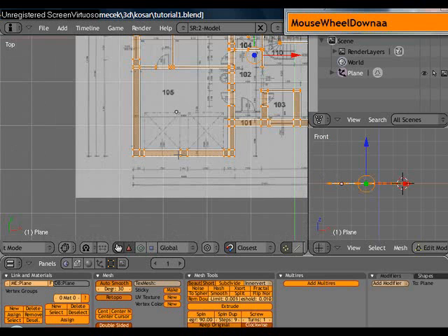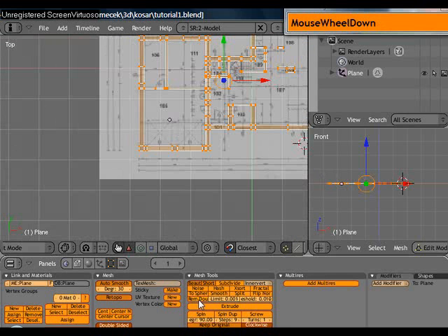To do that, I will select all the vertices, and I will use this Remove Doubles button. But before I do it, I will set my limit to 0. So I'm only removing doubles that are exactly on the same position, on the same spot, without any tolerance. If I would have some large value in here, the risk is, for example, if I would have 0.5 in here and I would have those two 0.4 apart, Blender will merge them and replace them with 1, which is somewhere in the middle, the average of the two. So I like to avoid that.